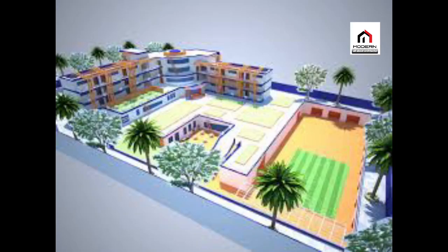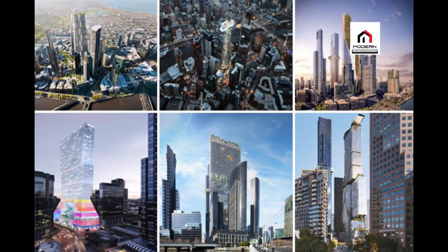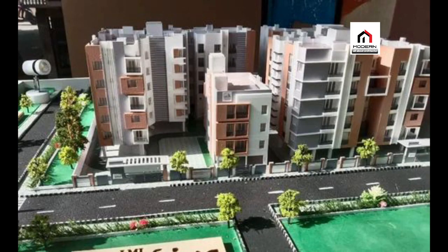Eighth, achieving the human scale of buildings and avoiding huge blocks inside city centers. Permeability to pedestrian traffic means reducing the size of the blocks and increasing the number of roads and corridors within one neighborhood. Permeability of natural lighting and ventilation into the buildings by reducing the size of the building mass compared to the area of the facades.